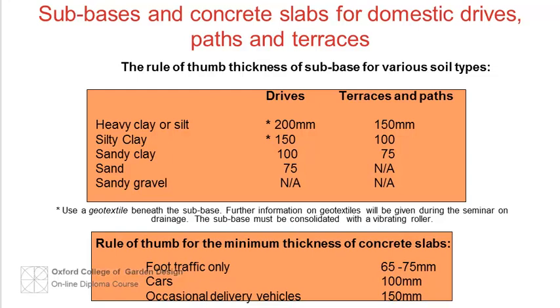A subbase is the name used to describe a consolidated layer of aggregate laid to form a foundation for a drive. The materials used for a subbase are further discussed in the seminar on stone. A subbase is important because it supplies part of the overall strength of the paving.